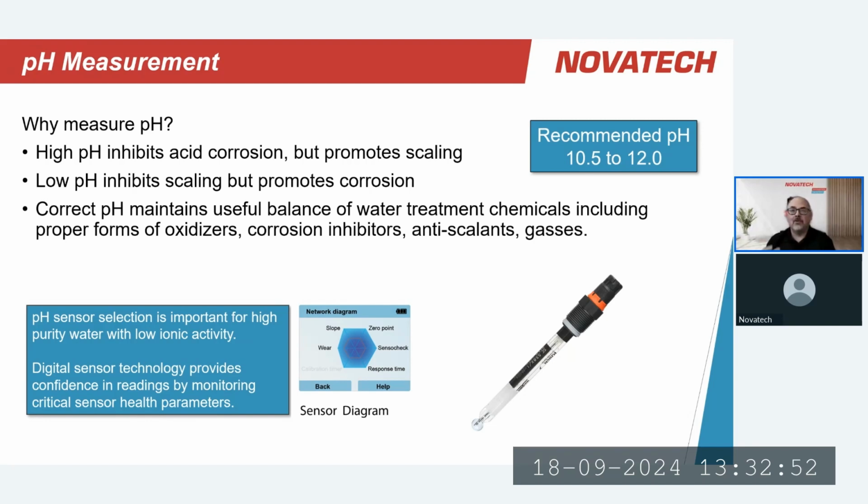So with these types of instruments, normally the only way to ensure that the instrument is working properly is to validate it with a known standard. So you perform a validation or perhaps even a calibration. But the comfort that comes with digital instruments is that you can see that between those checks and ensure that, yeah, the sensor's checking itself, it's looking good, it's happy, I feel confident that this number is correct.